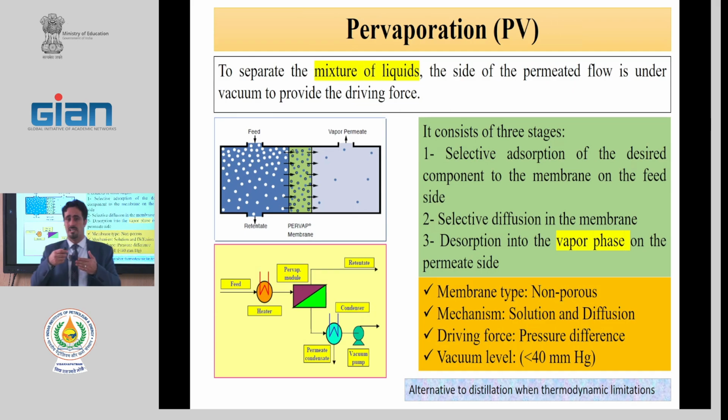For ethanol and water at the azeotrope, we heat to about 50 to 60 centigrade, not reaching boiling. We want to reduce the energy consumption. With increasing heat, some of the ethanol can change to vapor, and the vapor passes through the membrane.